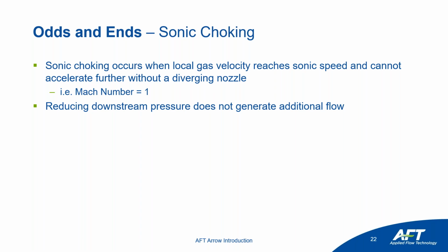You have this limitation on your delivery conditions. What changes do you need to make, or are you still able to meet your delivery conditions with that sonic choking in place? The big picture is when you are sonically choked, if you further reduce your downstream pressure, if you're trying to increase the amount of flow by reducing downstream pressure, that no longer is effective. You no longer generate that additional flow that you're going for.